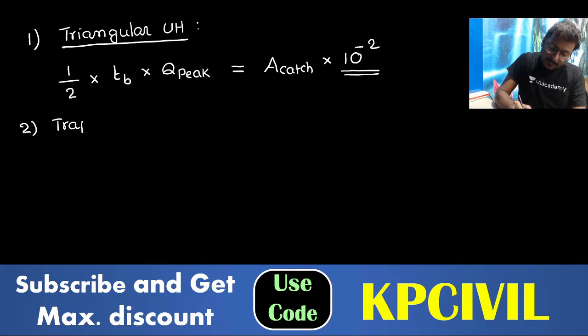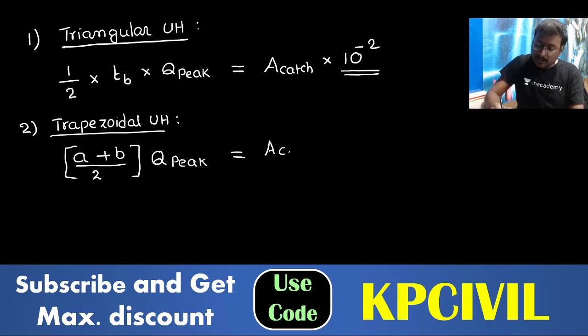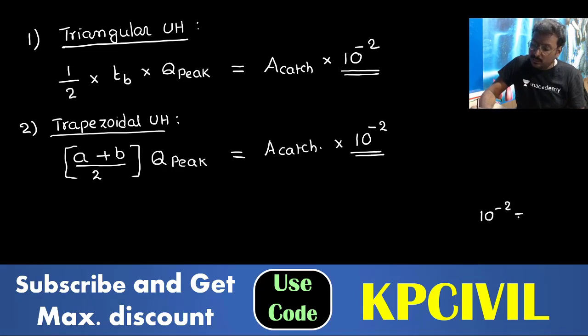Same you can apply for trapezoidal unit hydrograph. What is the trapezoidal formula? (A plus B) by 2 into peak discharge, peak of unit hydrograph, peak discharge, which is equal to the same area of catchment. What is changing then? Direct runoff hydrograph formula, unit hydrograph formula, what is changing? Instead of ERF depth, you are taking 10 power minus 2. 10 power minus 2 is equal to 1 centimeter. That is in meter, you are taking 1 centimeter.